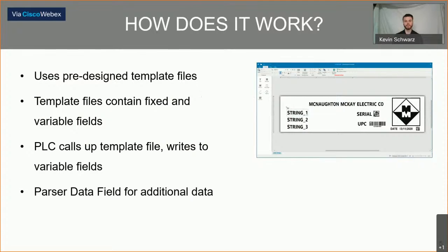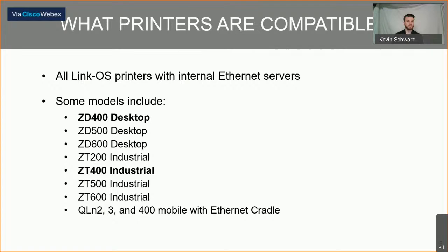There's a parser data field for additional data. Or if you wanted to send the entire ZPL file rather than using a predefined template, you could also send the entire ZPL file via this parser data field. And again, that's just an extra space to be able to write to the printer from the PLC.